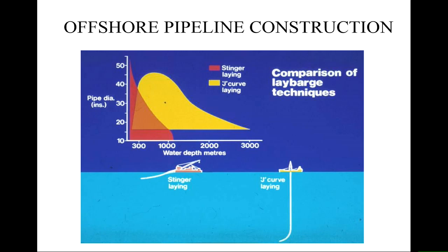That's mostly used where the water depth is not very big. If we go to deeper water, we use a J-lay approach, and in J-lay the welding is vertical, and we go down, and then it goes horizontal at the bottom, shape of a J. So S-lay and J-lay just really is the shape of the pipe during the process. And J-lay is deep water and S-lay is shallow water, and there's some overlap between the two.